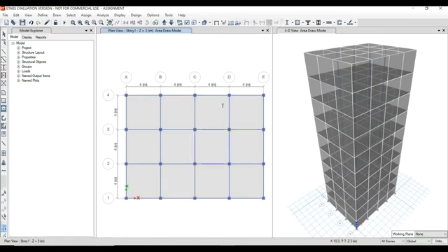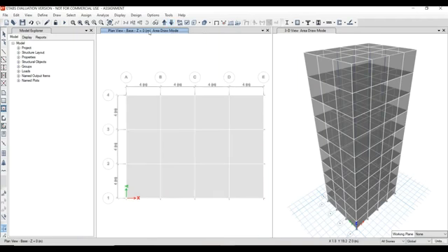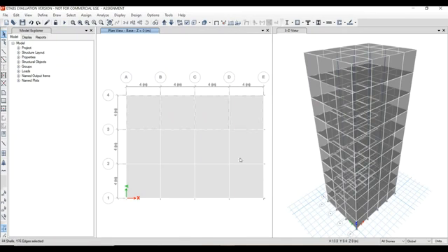And now we need to assign the loads. Before assigning the loads, we need to make sure that the base is a fixed base. To give that as a fixed base, go to base, plan view, z equals 0. In that place, we have the slab floors, which are already assigned due to selection of all stories. Now select the individual stories. Delete this one, click escape, and now select every panel. So every panel is selected.